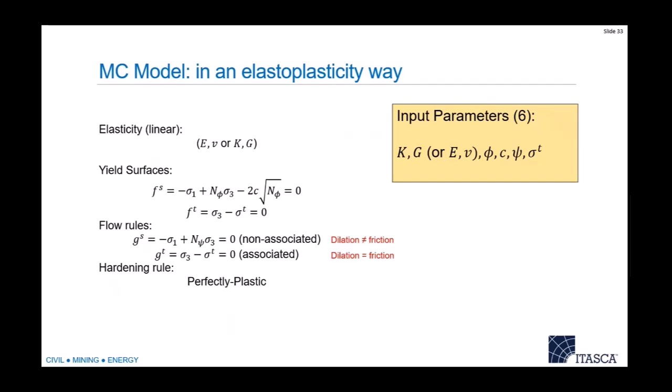Same thing could happen in a soil that has not got a joint in it, right? You're sort of forming this failure band or something like that. So essentially this thing is shearing and it could potentially start to dilate, right? That's a relatively well-known phenomenon, especially in something like a sand where you might have some dilation. So the way that the soil behaves after it reaches the peak strength depends on its dilation.